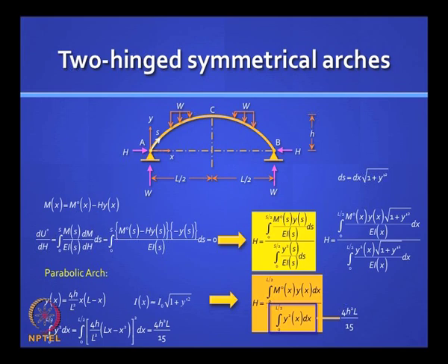Okay. First question, let us say you got an unsymmetric loading, do not worry, make it symmetric because then you need to integrate only over half, find out the horizontal force and then divide that by 2 to get it for the original problem. Secondly, in this integration the denominator simplifies to 4h squared L by 15. Now let us say you have a case where you have a parabolic arch subjected to a uniformly distributed load along the horizontal span. Do you know the answer for that?